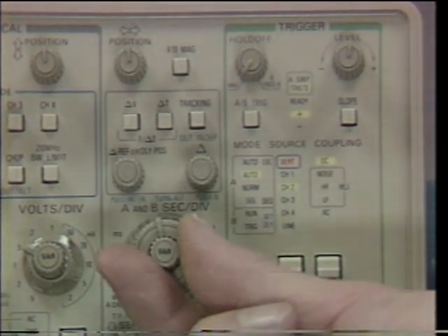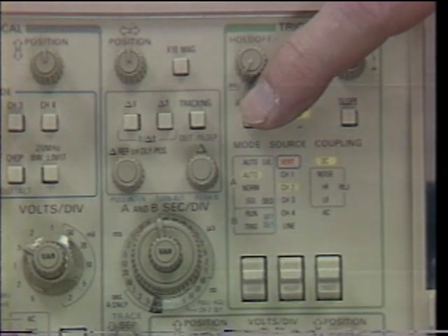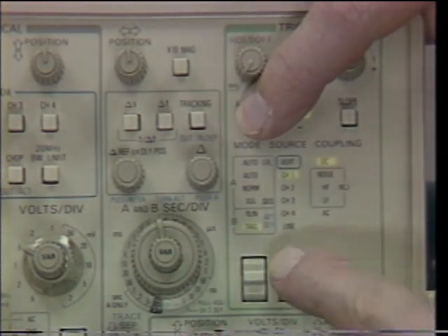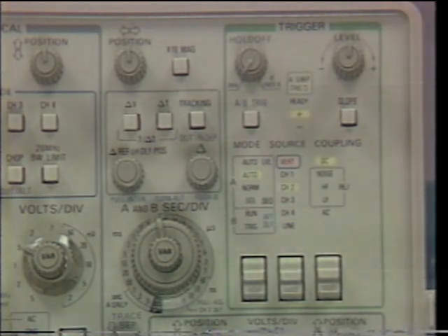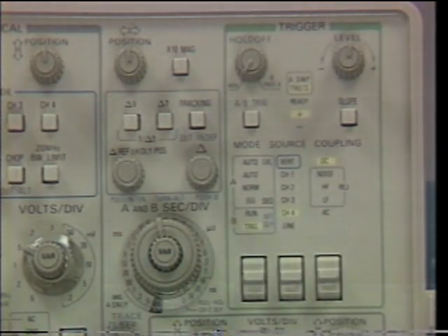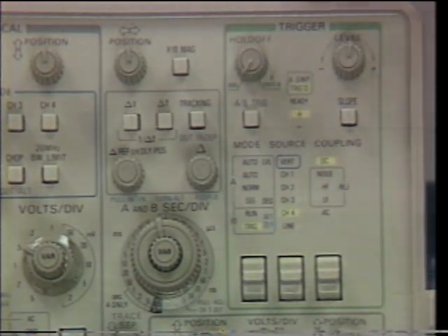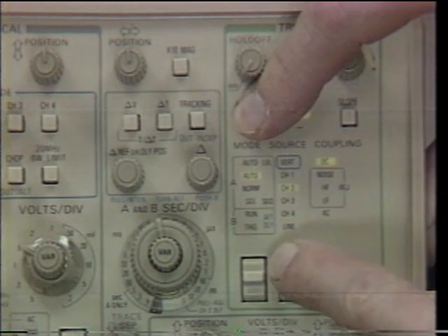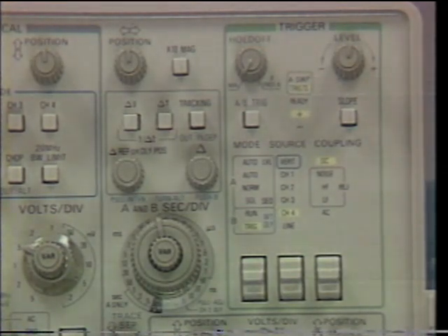Finally, even though the knobs may be locked, we can take a look at, and in fact change, if we so desire, the B trigger by holding the AB trig button depressed while we're making those selections. But unless the B sweep is displayed, those have no effect. Likewise, while the knobs are unlocked and the B trigger after delay mode is selected, we can take a look at the A trigger and modify it without affecting the B trigger. And then when we release the button, the controls are immediately reverted to the B trigger.